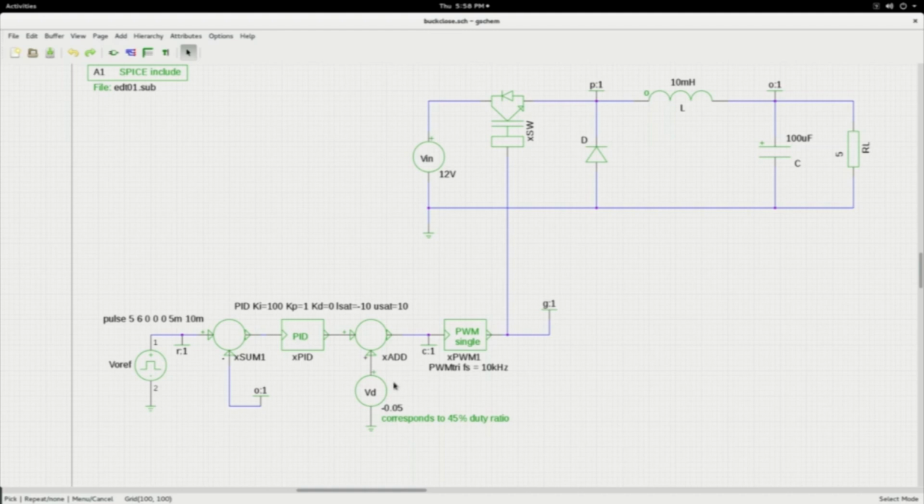This is the nominal value, or the operating point value, which I am giving as a feed forward term, and this plus this will be the control voltage, which is D plus D hat, with even the variation that is coming due to unwanted reasons and is coming from the controller. This goes into the PWM and controls the switch. So this is how we add this feed forward term here.